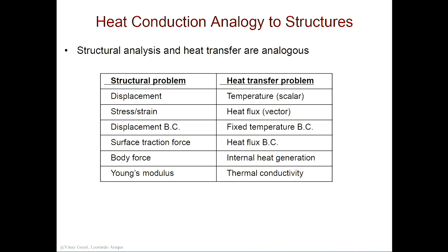The boundary condition in structures is a displacement fixed, or you apply a displacement. In this case, it's a fixed temperature. I apply a temperature to a node. In a structural problem, a traction force that you apply is in essence a heat flux that I apply in heat transfer. A body force in structural problems could be gravity, but in heat transfer it is internal heat generation.